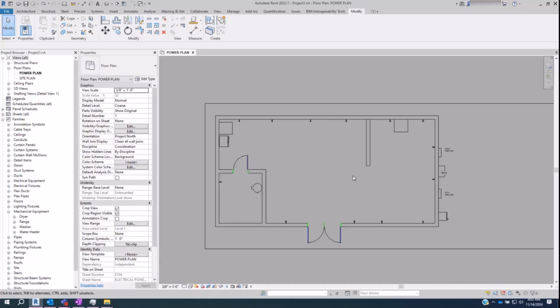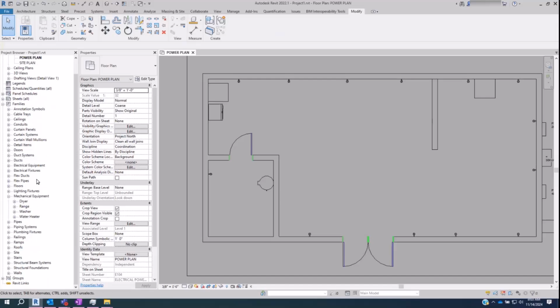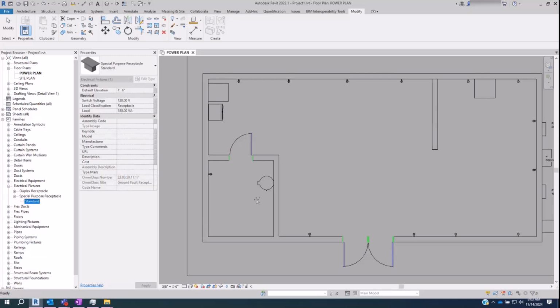Assuming they were already there because the mechanical people magically put them there, we need to power it. Now on full-fledged buildings, like commercial buildings, things like the water heater will need a disconnect most of the time. However, in residential areas, we can just use a receptacle. I brought in an out-of-the-box receptacle for special purposes, but I haven't messed with it. No idea what it's going to look like, but I know it's going to be wrong.